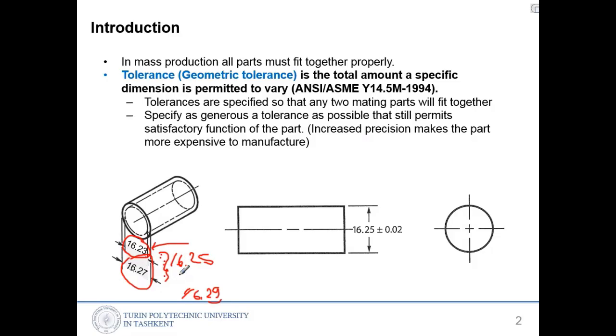And if you set only 16.0, without tolerance, you cannot produce this. How would you get this exact 0? If you see this under the microscope, you will see some deviations there. So you need to give a region, the tolerance region, with a bigger value and a smaller value. Then you are allowing it to be inside of these values.